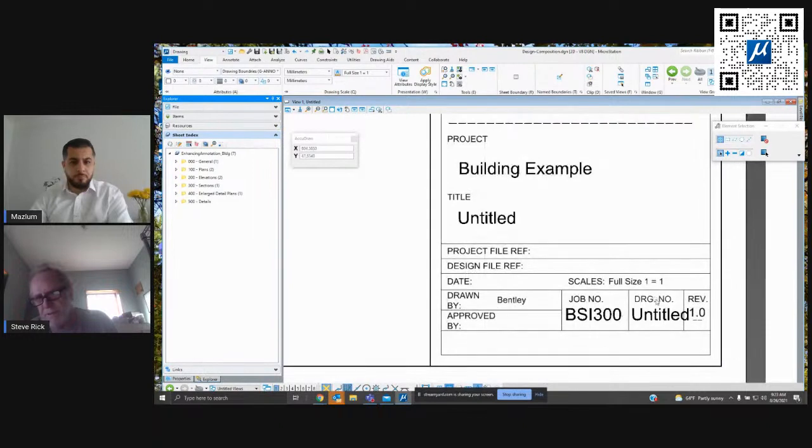So here's the title block, the drawing number, right? I want to do this. When I bring this into the sheet index, it automatically numbers my sheet. Now, this could entail a number of different numbering methods. If you want to number yours, this is sheet 1 of 200 and 2 of 200, you can certainly do that. I know a lot of customers abandoned that method because we didn't have a very good way to automate that. But we're going to bring it back again.